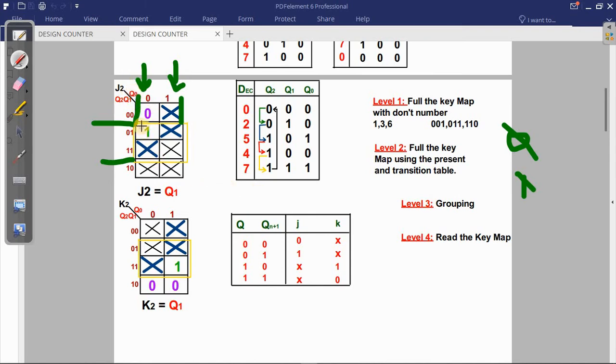Because my group is on both sides, on 2 columns, column 1 and column 2, I'm going to read all of this part. For Q0, if I check my group on these 2 sides, Q0 will load 0 and 1. Like I said, 0 and 1 cancel, so this 0 will cancel this 1, which means Q0 is already out of our answer because everything cancels, 0 cancels 1.